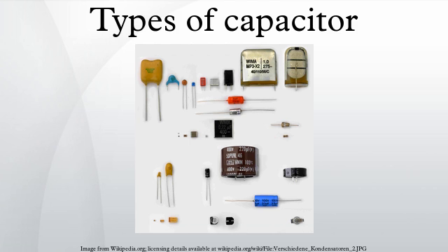Within electrochemical capacitors, the electrolyte is the conductive connection between the two electrodes, distinguishing them from electrolytic capacitors, in which the electrolyte only forms the cathode, the second electrode. Supercapacitors are polarized and must operate with correct polarity. Polarity is controlled by design with asymmetric electrodes, or, for symmetric electrodes, by a potential applied during the manufacturing process.